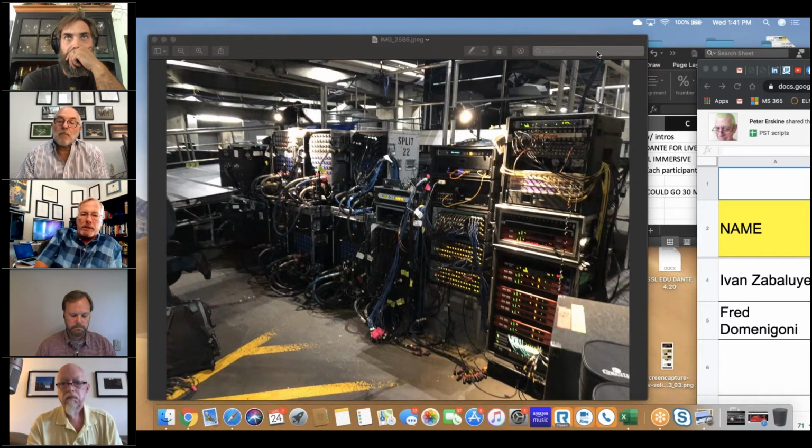So the challenge is to get everybody to agree to head amps, and we were talking about this yesterday with Kenny. The discipline to do this has to be that everybody agrees on a common gain setting, and it would go back to what we used to do, which is have one guy managing all the mic preamps for M3. This flow, as I call it, would require a single person managing the single type of head amp and then distributing that into a Dante network. Again, still back into a MADI stream up to the trucks because that's the transport protocol they subscribe to right now.